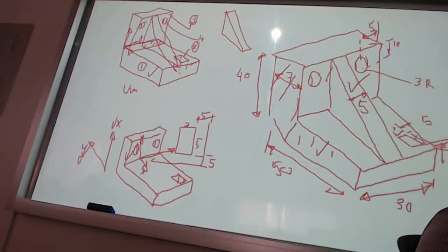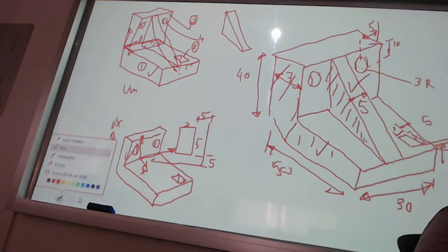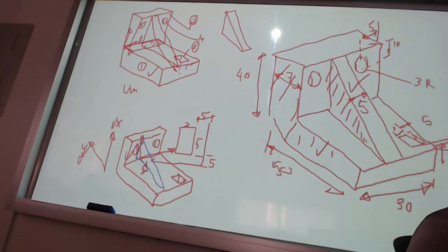I will just draw that triangular side of that wedge. Okay, so let's assume, guys, that I draw that side of the wedge. There you go. It's just a two-dimensional triangle. Okay, and then what is the final step? Exactly. So I'm going to make another press pull so I can make the wedge this way.